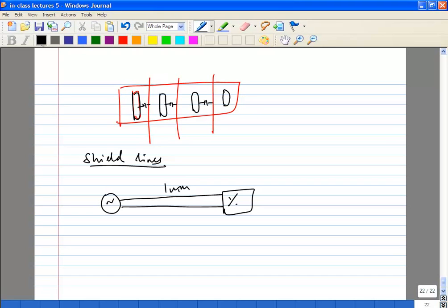You would make them very wide. Why? Oh, the resistance of the lines. Okay, so you want to make them wide because of the resistance. But what happens if you make it wide? Obviously, you'll have some extra capacitance, and you have to be careful, because if you add too much capacitance, then you'll be burning a lot of power trying to drive it.